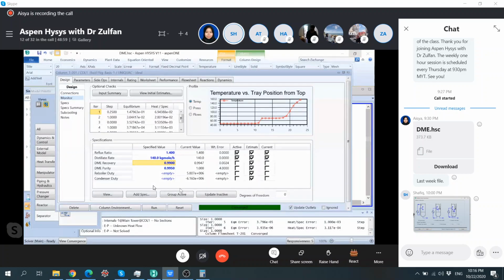In this case, I don't know, do you want to have methanol in your product stream or not? You could put that if you increase the distillate rate to 141. One minute, before you do this, escape. Okay, so memorize these numbers, the reboiler duty and the condenser duty. I don't know how you memorize it, but you have to memorize it.